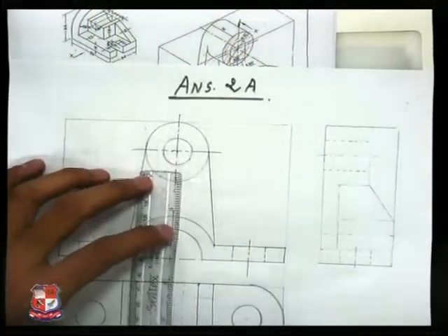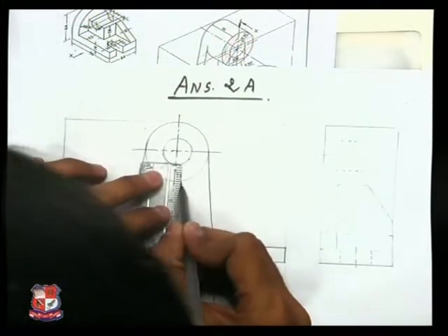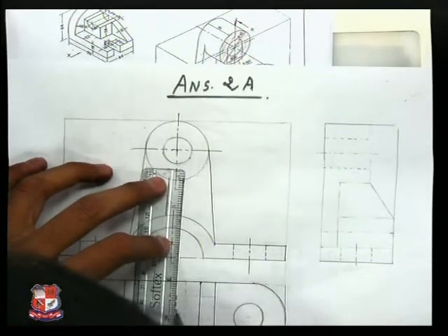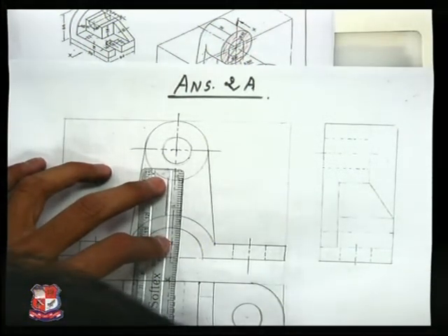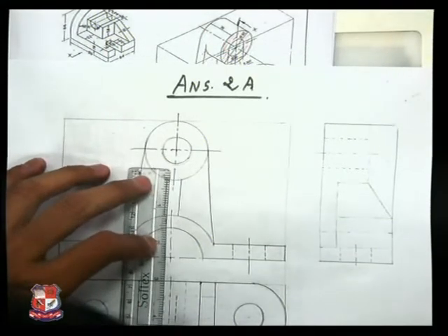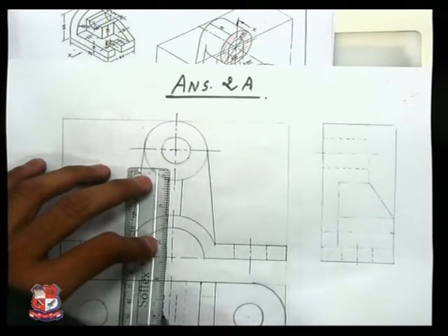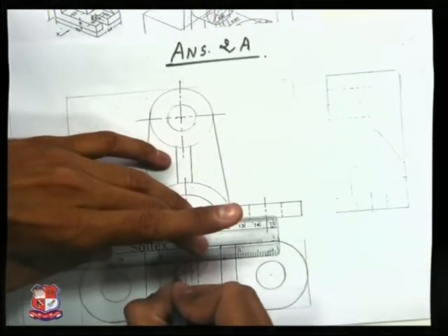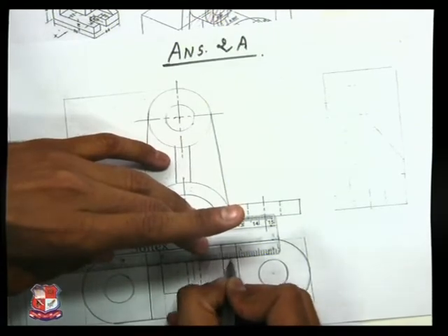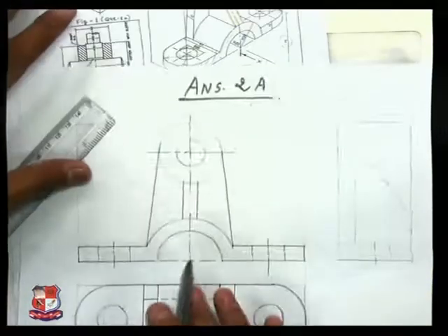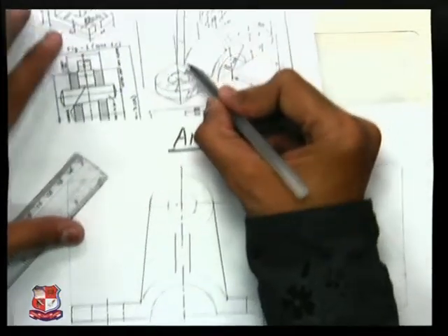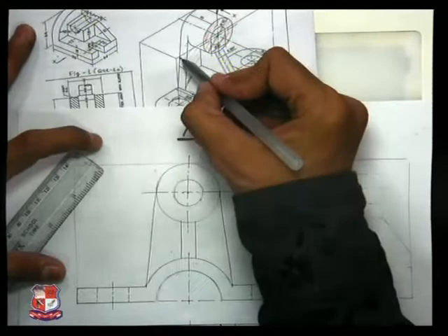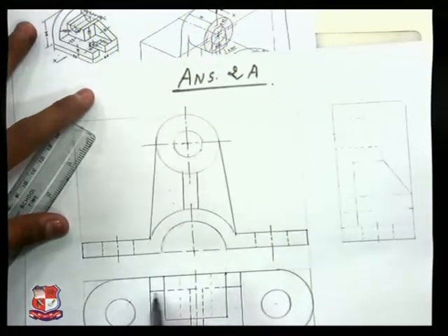So that to be represented in front view like this, and in top view with a dotted line, because it will not be visible when it is inside, it will be visible when it is outside. So this would be visible, this would not be visible, and here full line, then after dotted line, then after full line. If you look from the top side, this edge would not appear, hence we have represented it by dotted line. Up to this portion that would appear, so we have shown it by full lines.